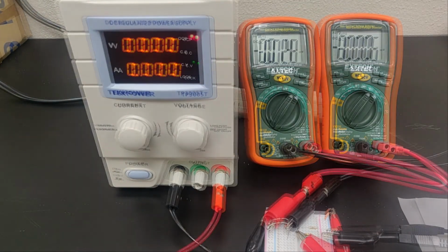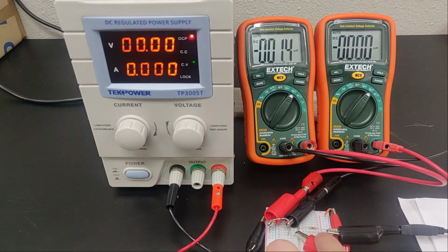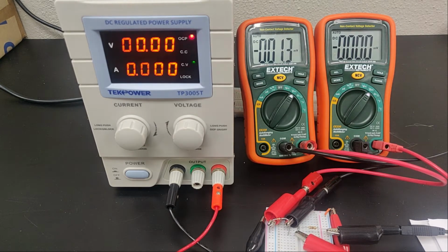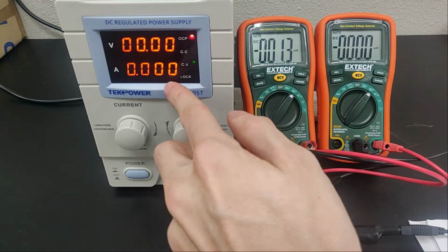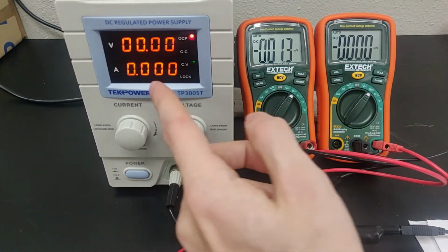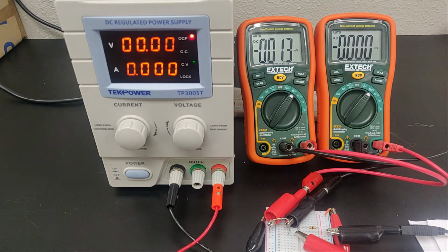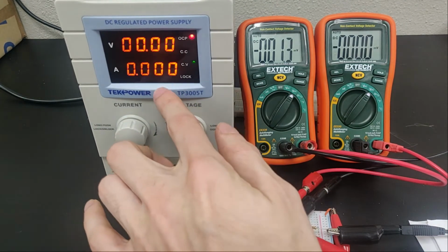So I've switched out the 100,000 ohm resistor with the 100 ohm resistor, and looking at the next part in the procedure, it's at step 8. It asks us to begin at 4 volts and continue sweeping in 0.5 volt steps on our DC power supply until we reach our current limit of 10 milliamps. So you should see at some point, even if we increase the voltage, it's going to stay constant, and that's because our current limit has been set.